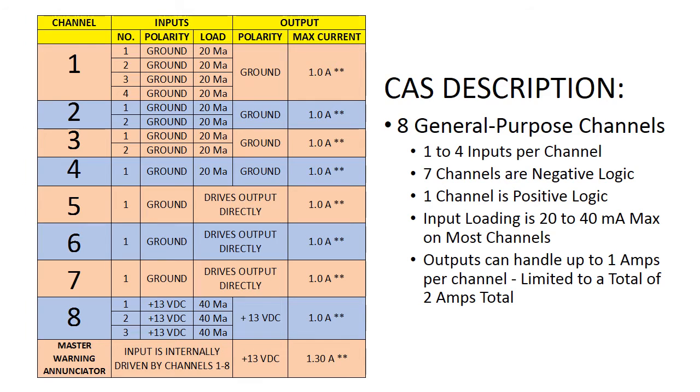So in addition to lighting a warning light and latching up my very bright sunlight readable Master Warning Annunciator, you could also have a voice playback unit that was saying warning, warning, and you could route that through your auxiliary input on your communication transceiver so that you would hear an aural alarm in your headset in case you were so distracted that 4 watts of bright red light in your face didn't attract your attention from the Master Warning Annunciator.